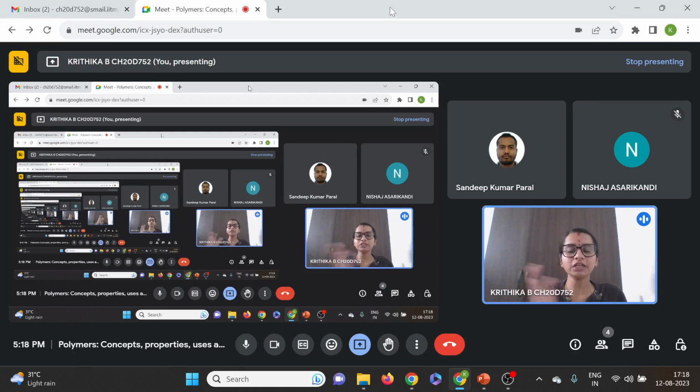So your Tg, the step you saw in the image. For example, if it is a blend of two polymers, the value will be somewhere in between. If one material has a glass transition of 60 degrees and another has a glass transition of 120, you may get the glass transition of the blended material somewhere in between, and whichever it is closer to tells you something.